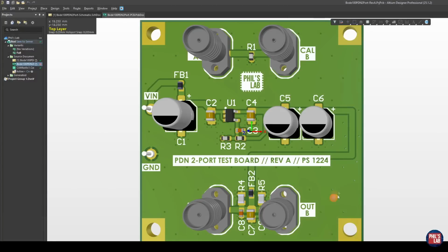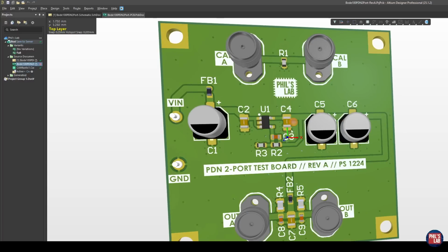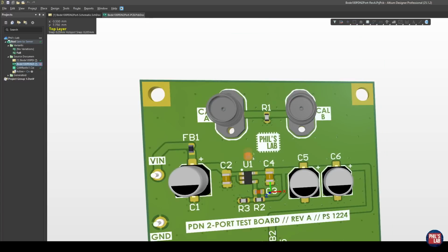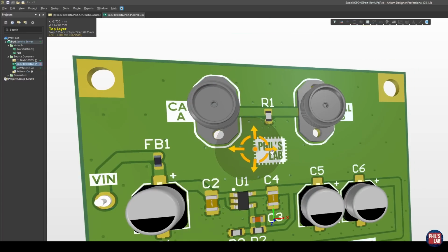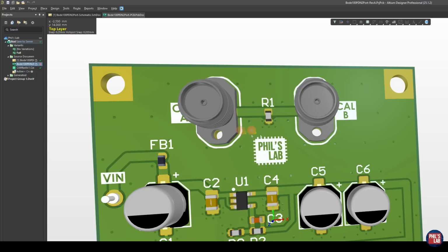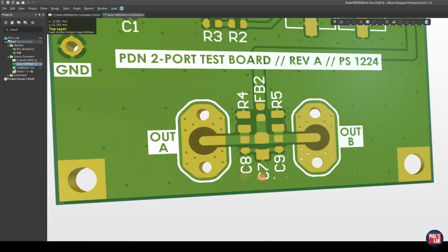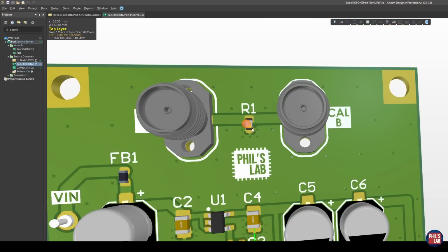In terms of measurement setup, because this is a 2-port measurement, I of course need 2 probes, and we also need to calibrate with an open, short, and load. The way I calibrate is to make a similar fixture to whatever my point of load will be. So right at the top here, I have these 2 SMA ports that I can screw on and clamp on. These are compression fit SMA ports, and they just clamp on to my microstrip features below on the PCB. This construction is to match the same construction of the point of load, that I have this trace running through and the connectors are spaced equally wide apart, so I have very similar calibration standards that match the point of load. Then I can either populate or not populate R1, so this could be my open, short and load standards, by placing different values of R1.